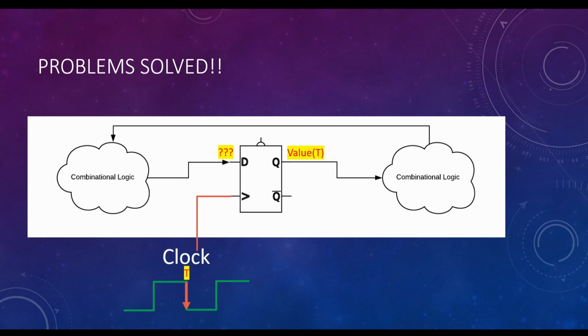And now the logic has a full clock cycle in order to stabilize. And throughout this time, the input to the combinational logic is not going to change. And therefore, we will no longer have this effect of continuously fluctuating values in the combinational logic, because at the root, the value is not changing. So no matter what we have now that is fluctuating on D, the output on Q is remaining the same until we get to the next edge, which is the edge at time t+1.